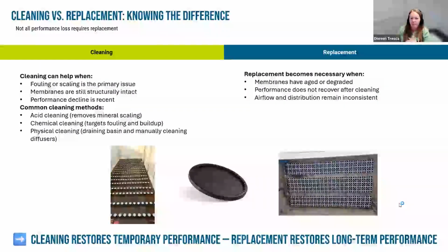We're also going to talk a little bit about when you know whether your issue requires just cleaning and maintenance, or whether you should be looking at a full replacement. Not all performance loss means you need to replace the membrane. If the issue is primarily fouling or scaling, cleaning can often help restore the performance of the diffuser.